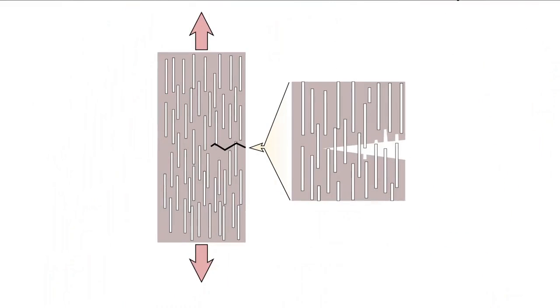With the likes of the composite depicted here, additional surface area to the crack flanks can be realized as fiber pullout. Instead of the fibers fracturing, they displace with the matrix such that they are pulled out of the regions immediate to where the crack is propagating. While the fibers can pull out of the matrix and remain unbroken while the crack is propagating, there can be regions where the fibers are bridging the crack. That is, fibers remain firmly embedded in the matrix on either side of the crack.